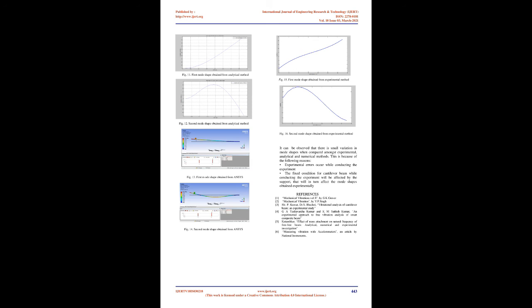This is because of the following reasons. Experimental errors occur while conducting the experiment. The fixed condition for the cantilever beam while conducting the experiment will be affected by the support, which will in turn affect the mode shapes obtained experimentally.